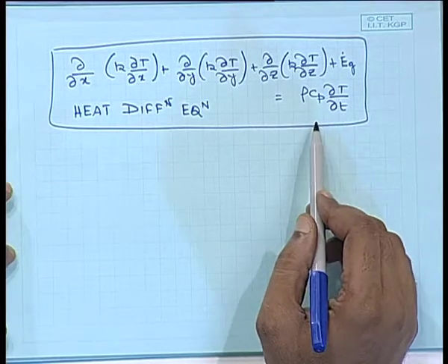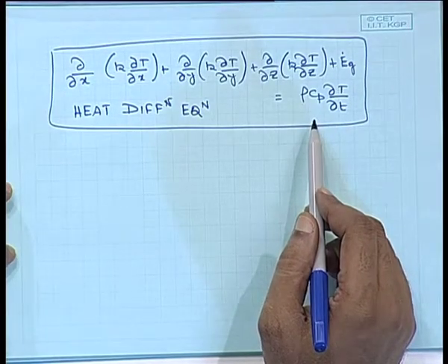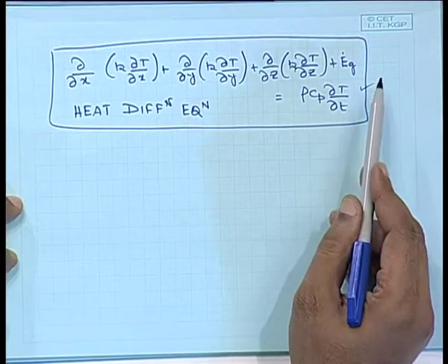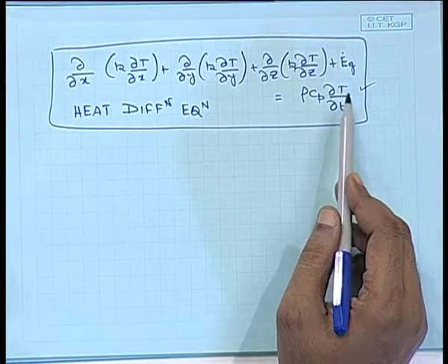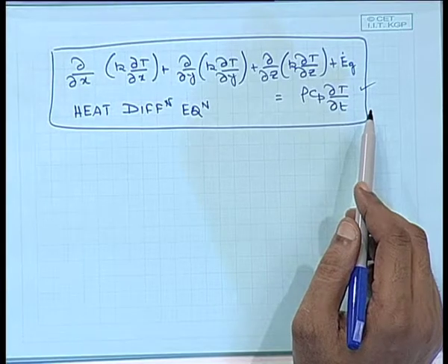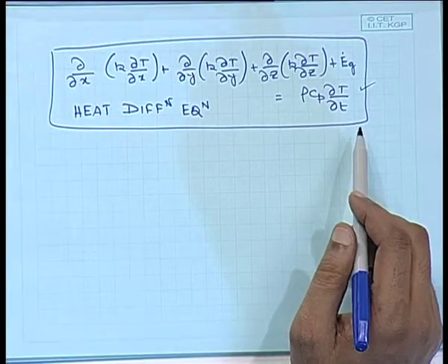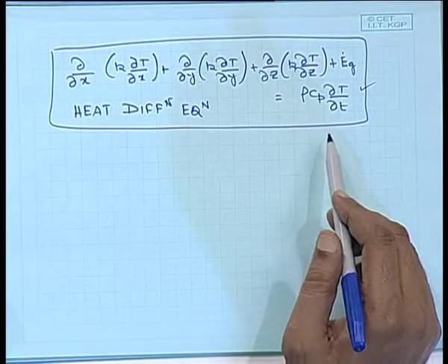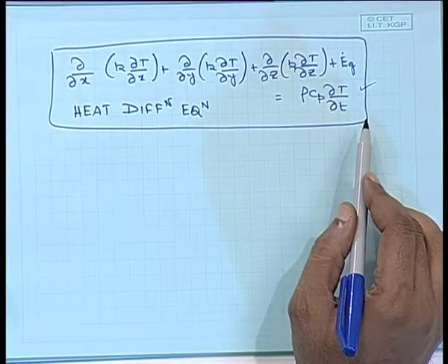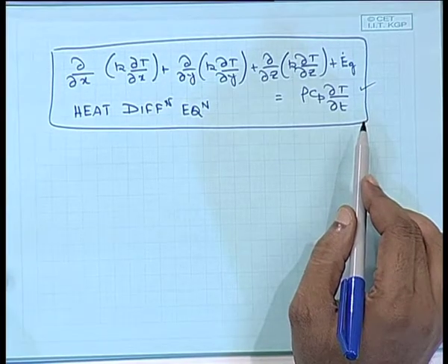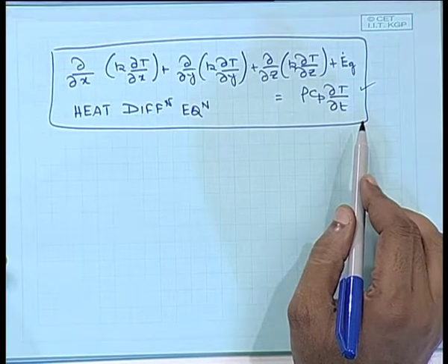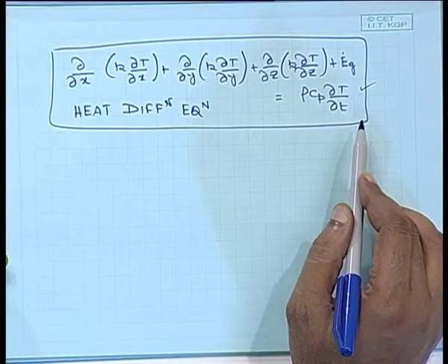Okay. So this is the most general form of conductive heat transfer inside a solid object, and similar to this one, which is in Cartesian coordinates, I can also have the same expression for cylindrical coordinates and for spherical coordinates, which are given in your text. I am not going to go into the derivation of that. So transformation of coordinates would give rise to a slightly different form of this equation, but the basic concept would still remain the same, that it is going to be in minus out plus generation is equal to the rate of change of energy storage in the system.